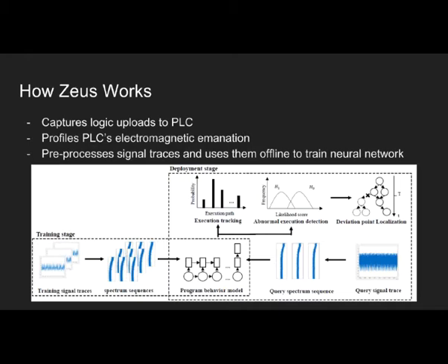We did some work in my group with really tiny microcontrollers, looking at the power line and EMI. We could make some distinction on data values, like if you were moving one register to another and the register was 0 versus some other pattern. We could make some distinctions there, but it's incredibly hard to do. With EMI, I would be surprised if you could ever do that.